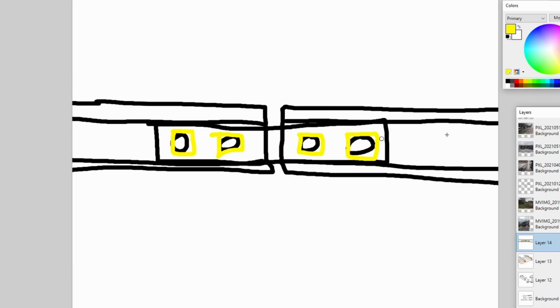You'd have joint bars on either side. Sometimes they're even meshed to fit the profile of the foot and the head so that they sit in place and can't move. You then have the holes drilled, you stick different bolts through, and you can hold your track together. This is the most simple way to fix your track.